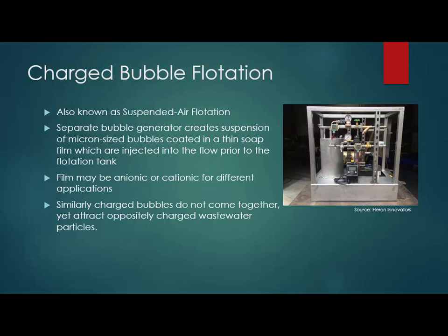Now this film may be adjusted based on whatever constituent you're trying to remove to either be anionic or cationic to fit the application. One advantage of this process is that because the bubbles are similarly charged, they're less likely to come together or coalesce. Yet at the same time, they attract the oppositely charged particles in the wastewater that you're trying to remove.